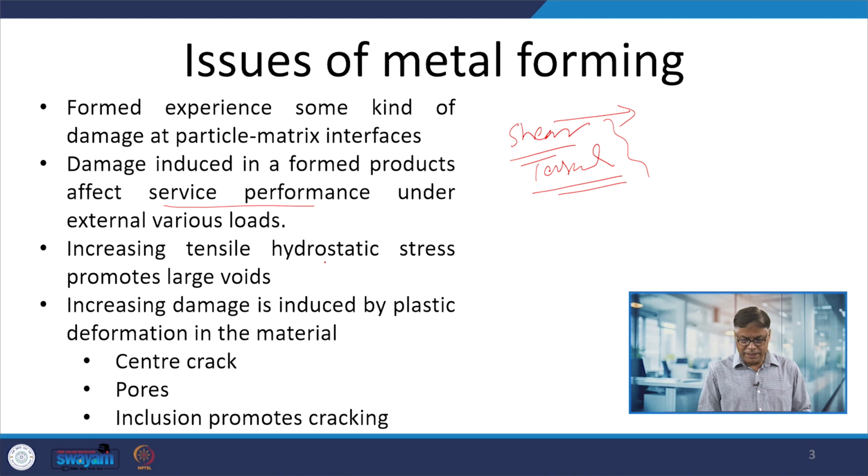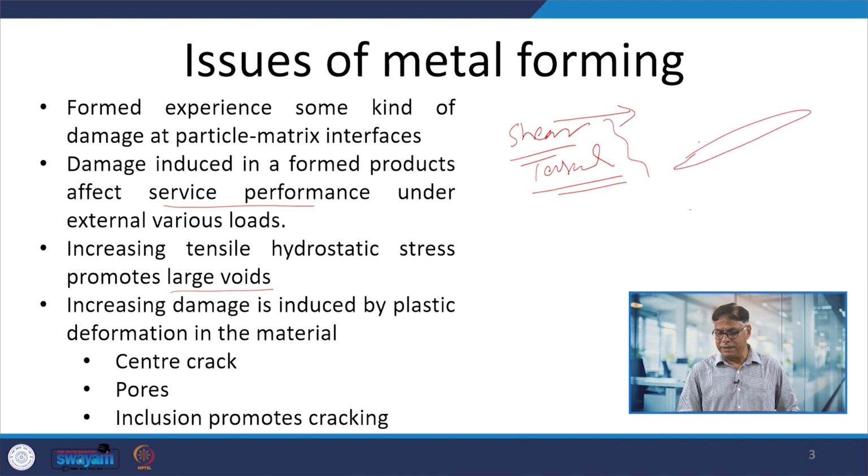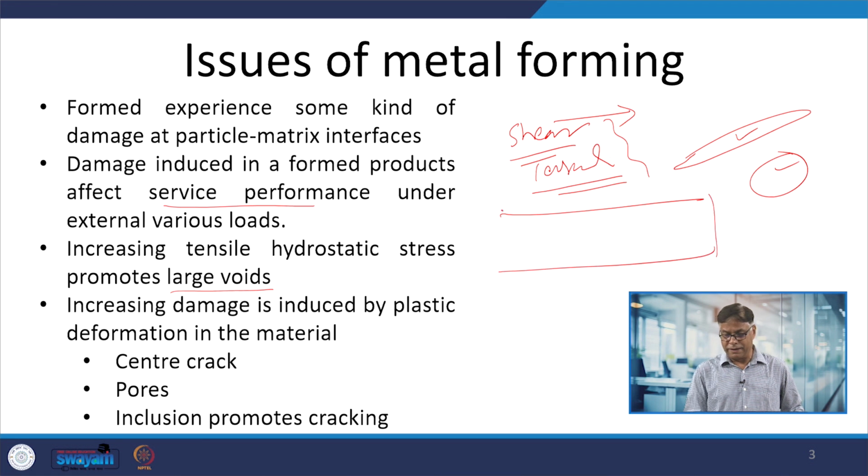Increasing tensile hydrostatic stresses promotes the void formation. So, if we have needle shaped particles or circular shaped ones, in all the conditions this kind of void formation can take place because of the differential properties of the particles as compared to the matrix subjected to the common plastic deformation. So, increasing damage is induced by the plastic deformation in the material, and that can appear in the form of a crack at the center, say.